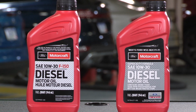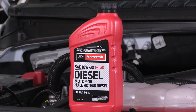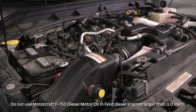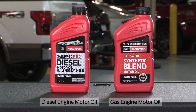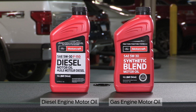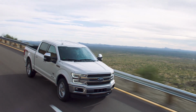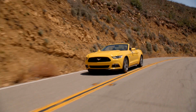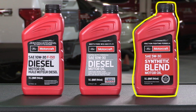In general, it's important to avoid misapplication of oils. For example, using Motorcraft F-150 diesel motor oil in a Ford diesel larger than 3 liters could cause harm to your engine. Also, do not use any oil manufactured for a gasoline engine in a diesel engine, or use F-150 diesel motor oil in a gasoline engine. The oils for each engine type require different properties for the particular engine. Make sure to always choose the proper motor oil for your diesel or gasoline engine.